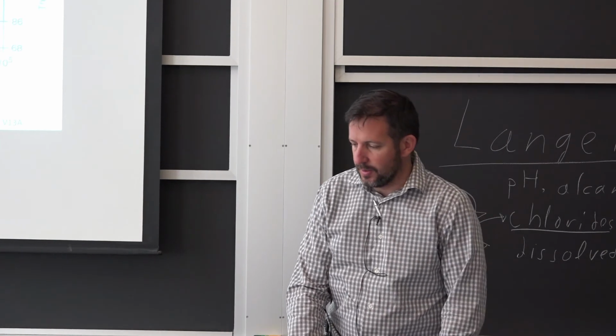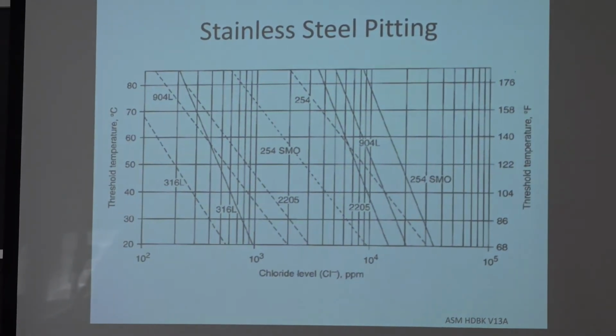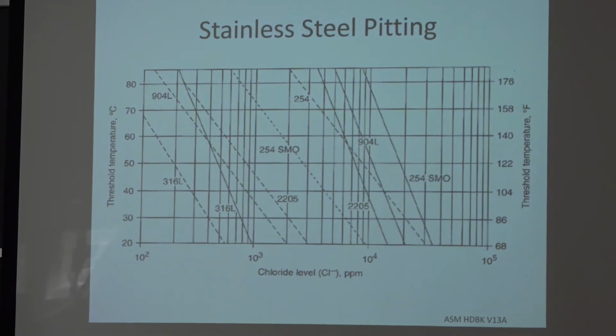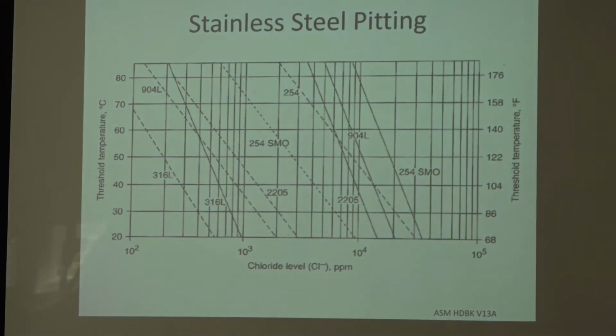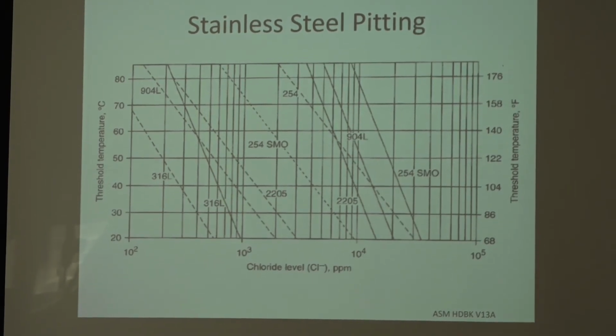It's on small boats, like sail boats. You can have all sorts of nice finishes in there, and they'll survive if you are willing to periodically maintain them with that soft, dissolvable lacquer. What happens with the lacquer is you do want to replace it. It will dissolve in alcohol. So when you say, oh, I'm starting to see a few rust spots, you go and remove the old one and you put a new one and you're good for another few years. That's the situation you have to go through if pitting is a risk for you.